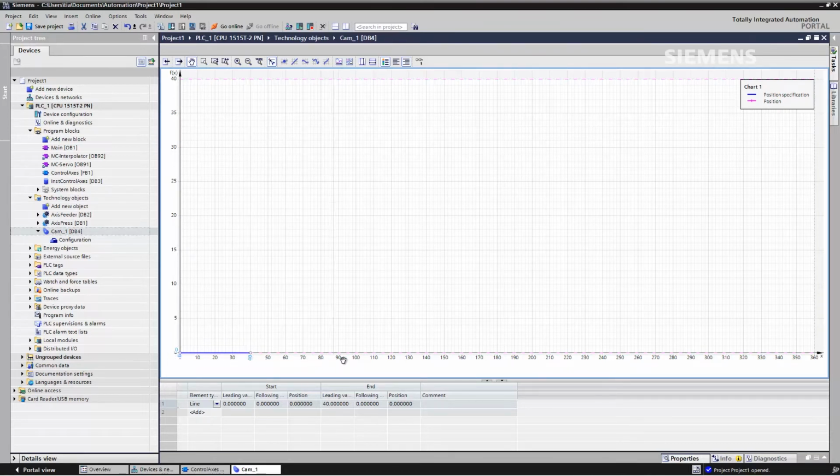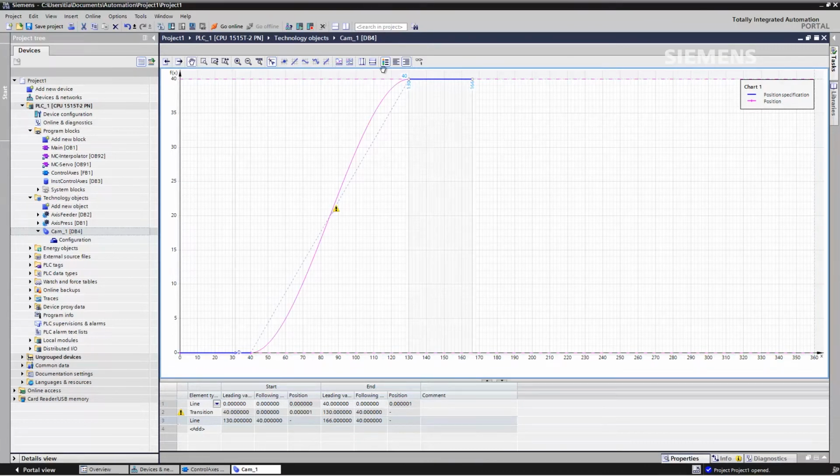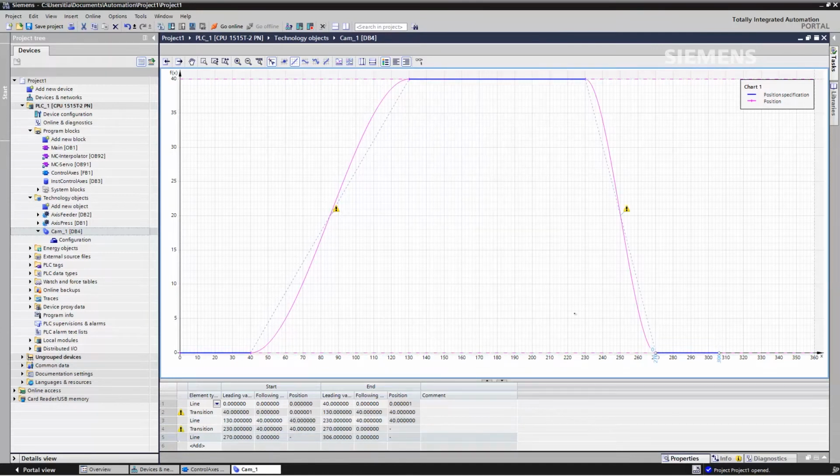If the press now moves farther, the infeed should then move forward. And if the press has arrived at 130 degrees, the infeed should stop at its right-hand position during the press cycle. That is, until the press has arrived at 230 degrees. Afterwards, the infeed should return again. And while the press is turning 270 degrees and 360 degrees, the infeed should stop on the left-hand side.